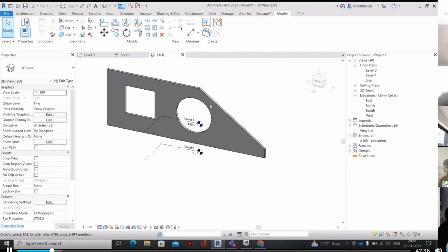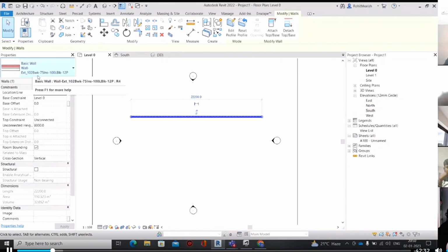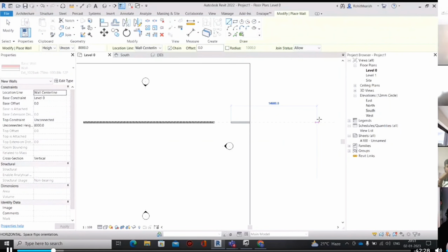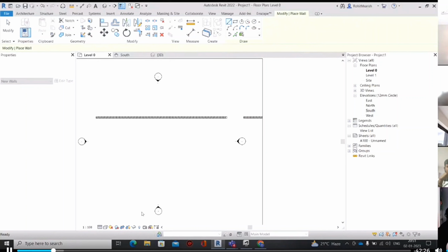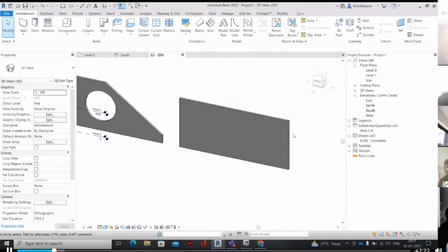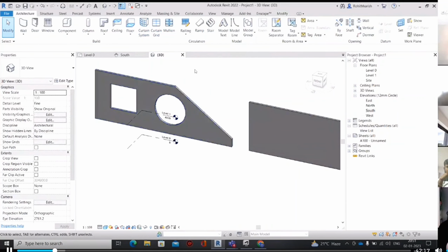So just to check and verify, here you can see I have this basic wall ext102. If I create the same type of wall somewhere on the right, you can see that it is being created perfectly the way it was, and this one is edited. That means we are playing here with instance properties. I hope we all are on the same page on this.